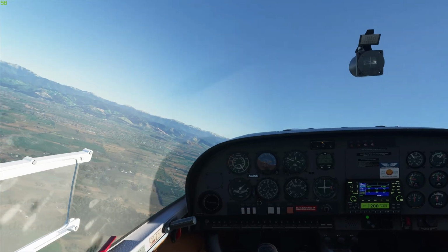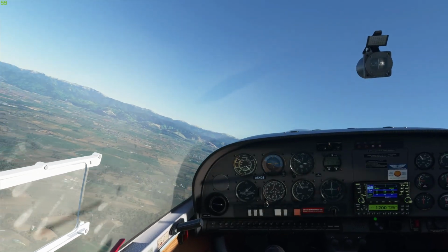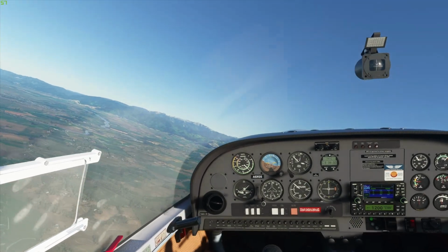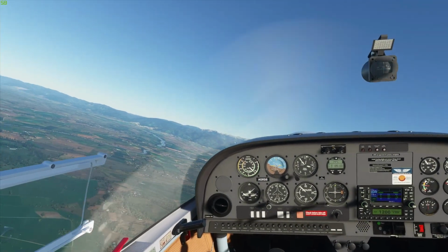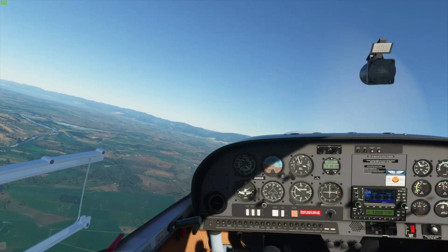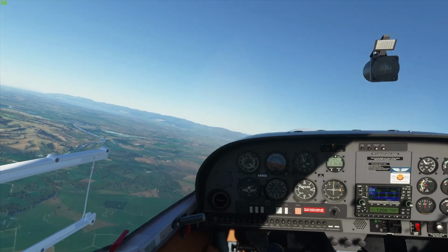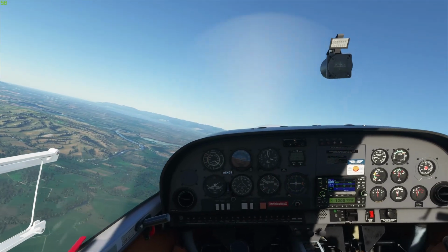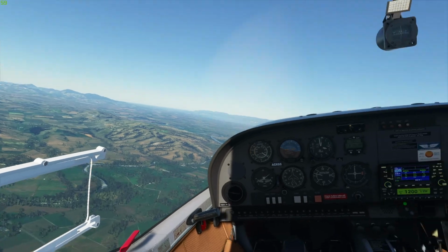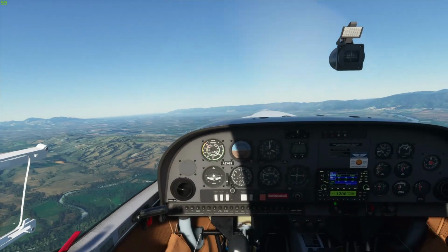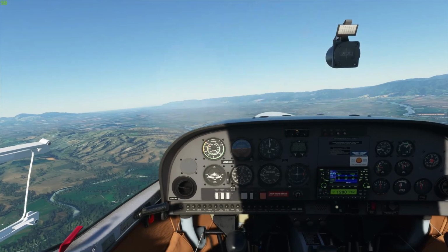yeah, so you could really recover any time prior to that without too much trouble, but I'm satisfied the control authority was good throughout the speed range, and that gives us a good idea about how slow we can fly this aeroplane. So in terms of an approach speed, we can just set up a dummy approach now from 3,000 feet, so I'll reduce the power to 15 inches. T's and P's are still in the green, we're in a good area. I'll just fly in this heading to avoid that rising terrain, and we'll set flaps, takeoff and approach.